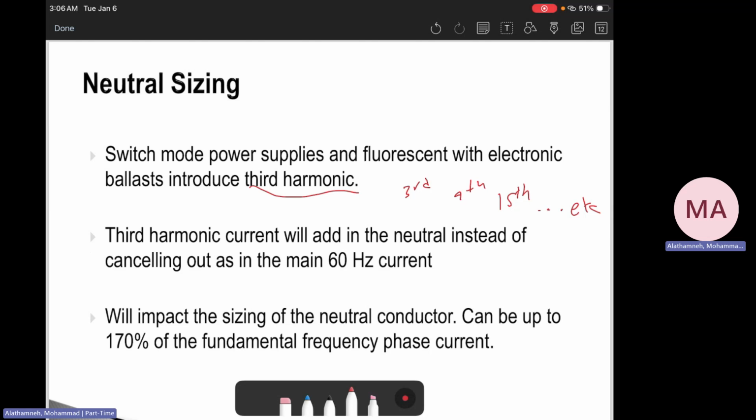However, in modern buildings, we don't size the neutral like that. We study the load harmonics, so the neutral size will be bigger, and it can handle these triplen harmonics. That's the difference between modern buildings and old-design buildings.